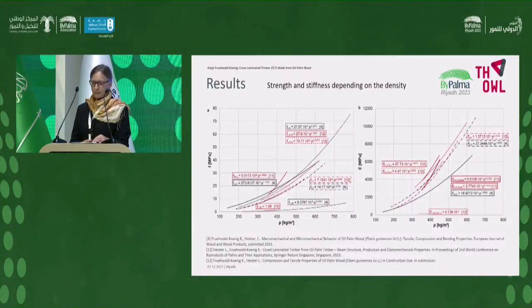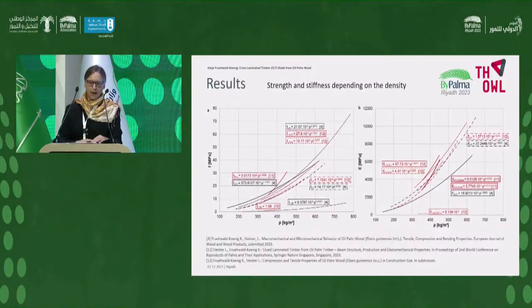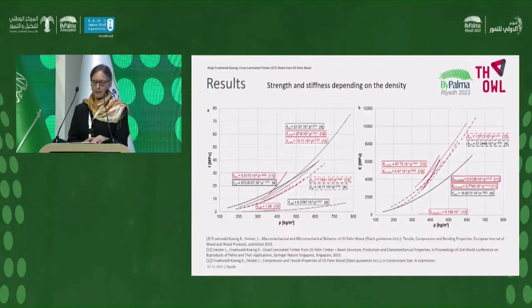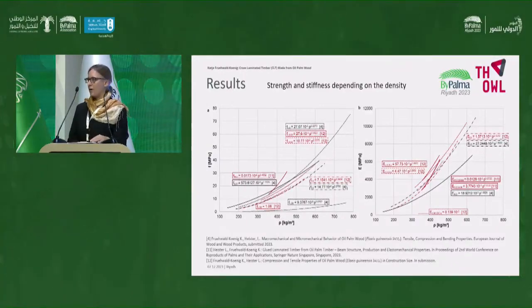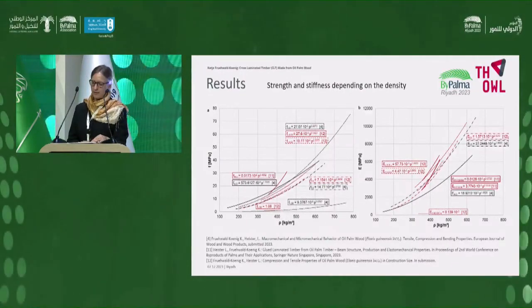In contrast to common wood species, the strength of the full-size test specimens in the left figure is above that of the small-sized ones for the compression strength perpendicular to the vascular bundles, and is in the same range otherwise. The large and the small-sized test specimens for the tension strength parallel and the bending strength are slightly below the compression strength parallel to the vascular bundles.